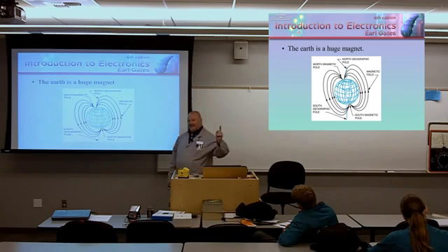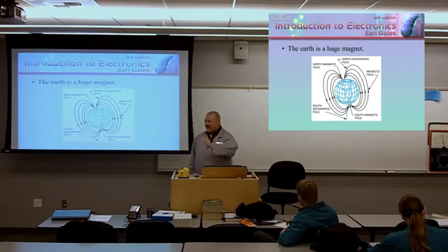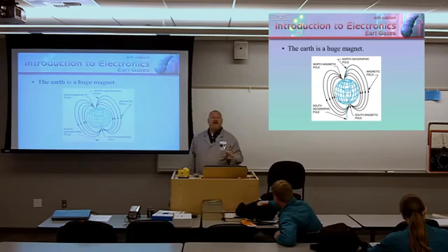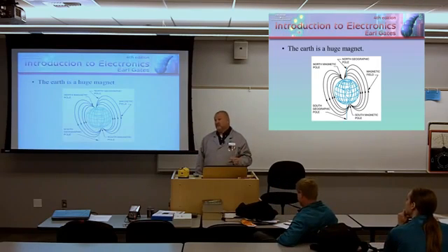I know because I'm a pilot. And it's kind of important. Okay, because if I start flying northbound or whatever, which am I going, geographic north or magnetic north? And the difference here in the Seattle area is between 19 and 20 degrees.